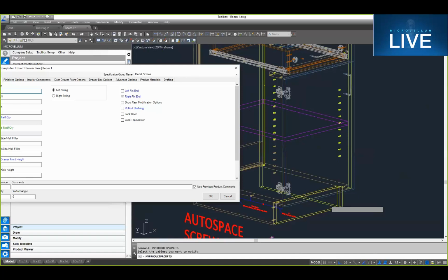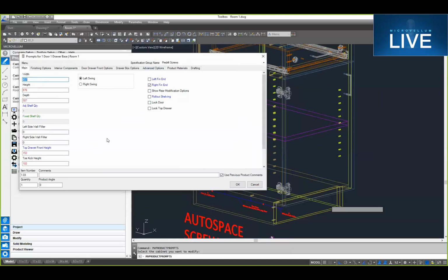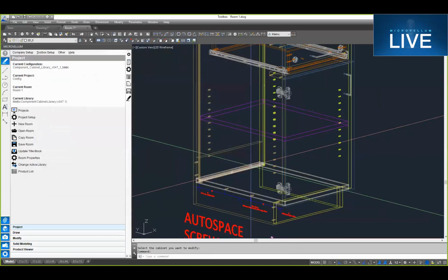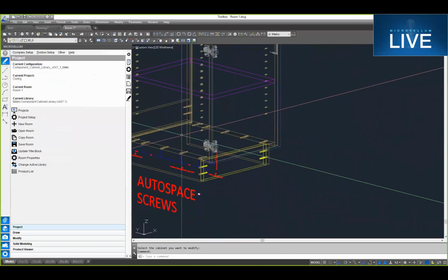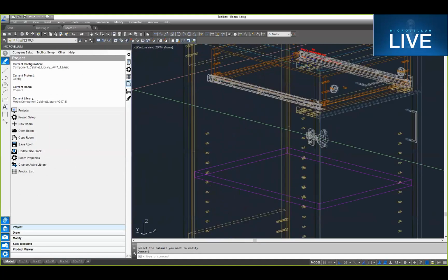If you're doing an integral finished end like this, where you're actually using finished material for the part, most often you're not going to want to drill through that to put a screw through it. So maybe you're going to replace that with some dowels or change how that's constructed. To do that, we can set up our settings so that as soon as we turn on left finished end or right finished end, when we're not using a post-laminate condition, we can drill only at those unfinished ends, and then use dowel spacing for the others. If we look at, let's say, this one, let me see if I've got that set up on here.